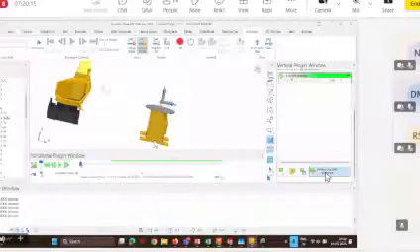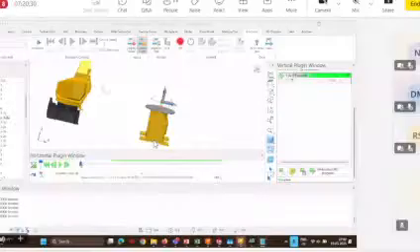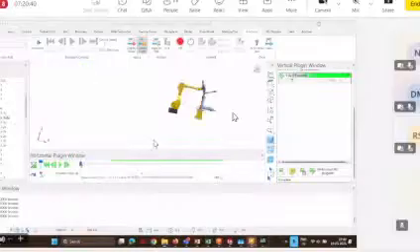If you open it, you can see all these commands, how it goes: the coordinates and the orientation of each point as per the end effector will be stated over here. Like this, you can create toolpaths for robots, take them directly to the robot, and start printing. We can even put in our own robot, like I said, and define the axes. Not only that, you can even develop your own robots, and the controller might be your own. For the same, you can generate a post processor from here only. So I hope it is clear how to generate toolpaths for robots.